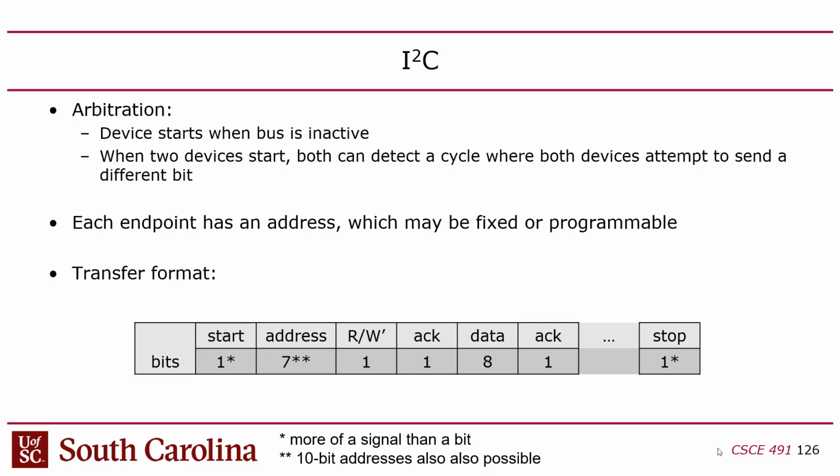Okay, now this is the part that's kind of strange and confusing. After you send the read-write bit out, there's an acknowledgement, but the thing that's crazy about this is that the acknowledgement uses the same wire as the address bits and the read-write flag, right? You might say, why is that weird? Because the acknowledgement is being sent by the other entity, the slave, right? So how does that work? If I'm the master and I'm controlling the data line, how is the acknowledgement working?